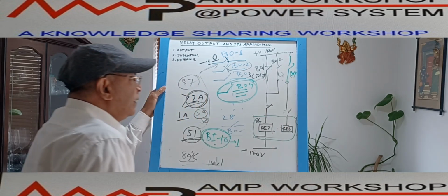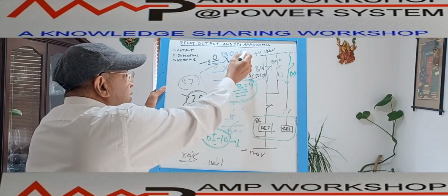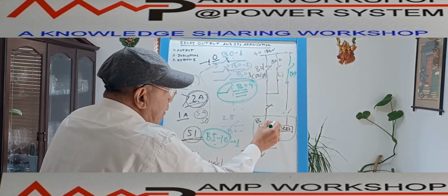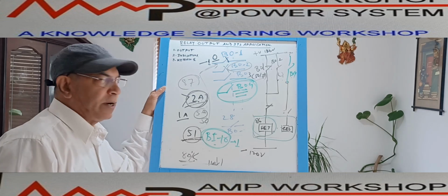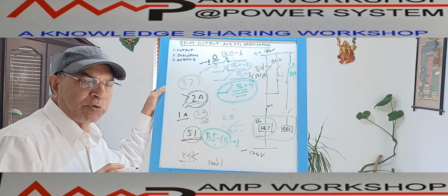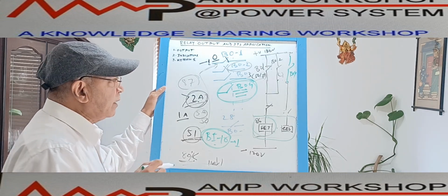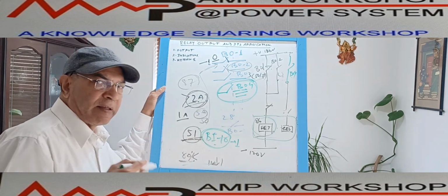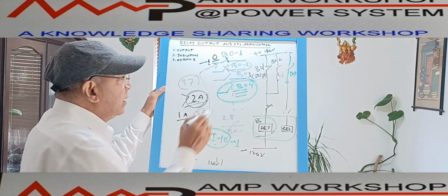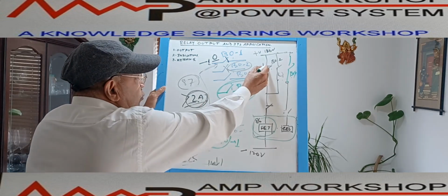Then what will happen? The moment these are activating, immediately the lockout relay set coil is operating, and the lockout relay operating gives an output contact, it will trip the breaker. After that, we have identified the fault and we have cleared the fault, then this overcurrent condition will get out.